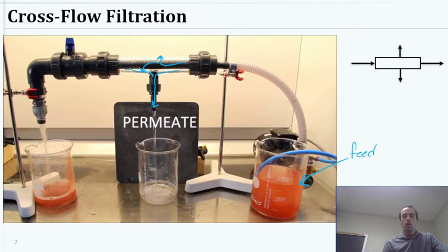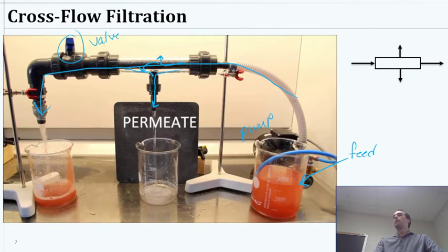And you see over here, we've got a pump in the background that's applying the pressure. So that's pressurizing our feed. We're applying it here. We have a valve here to restrict the flow of the concentrate, because otherwise water could just flow straight through here. It's like, I don't feel like going through the membrane, I'll just go straight out here, right? That would be its normal way of doing it, but that valve is going to restrict the flow, resulting in a pressure in this chamber.